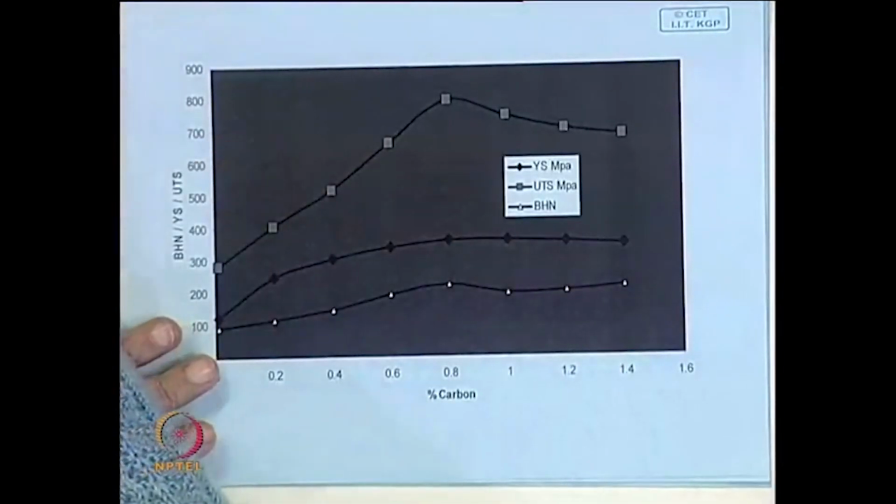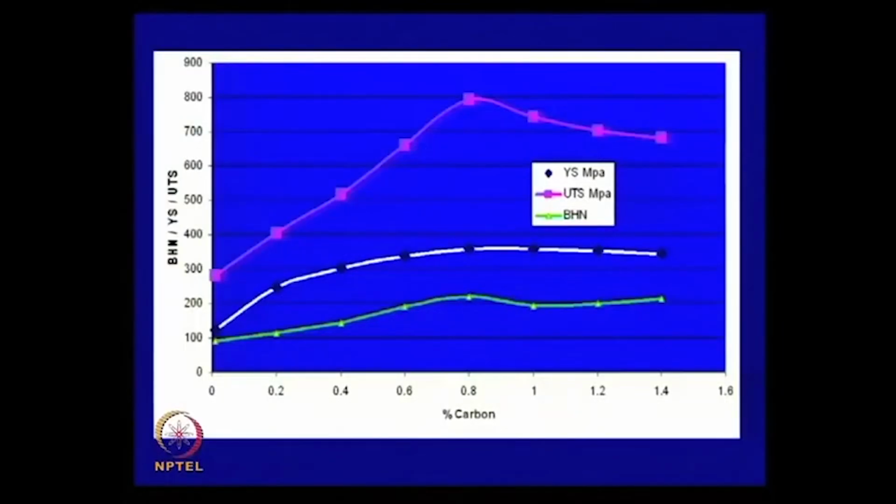I think the next diagram here typically shows what I talked about, you look at this with carbon content. I took this data from handbooks for steel which are cooled at a very slow rate, annealed steel, and this axis gives Brinell hardness. So, look at this part, the hypoeutectoid steel, it is very strongly dependent, but thereafter the change is not much.